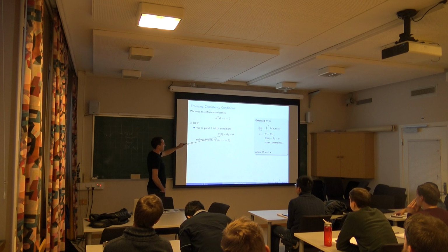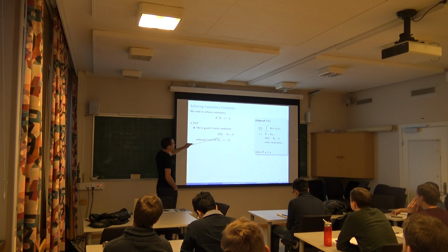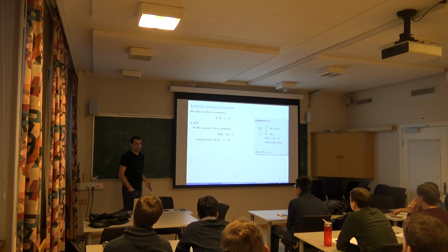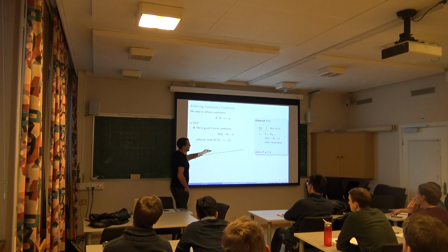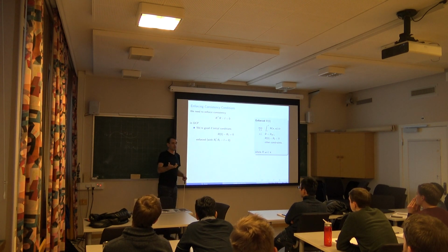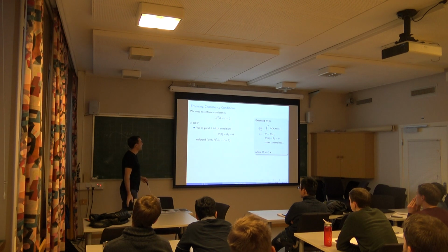All that matters is that the R0 that you assign, your initial conditions, needs to be consistent, right? As long as you do that, your R will remain a rotation matrix throughout the dynamics, right?